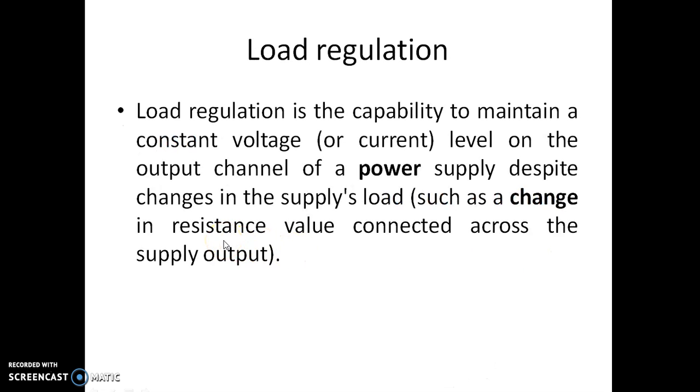Let us see what load regulation is. Load regulation is the capacity to maintain a constant voltage level on the output channel of a power supply despite the changes in supply load. That is, if you are trying to draw more and more current, the output voltage should remain constant.